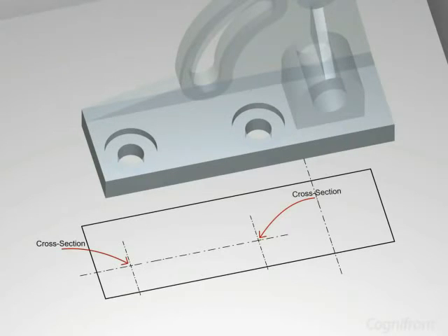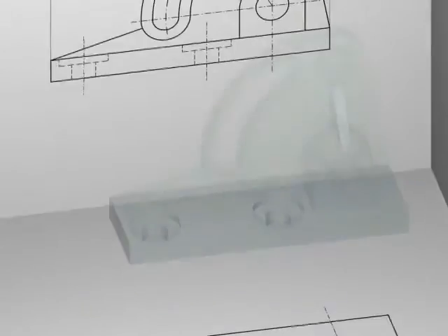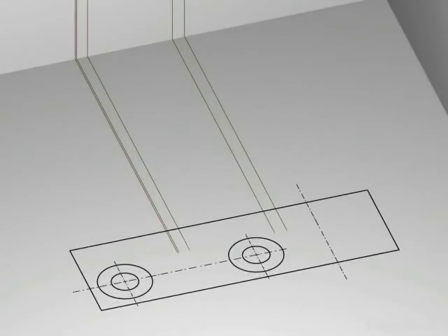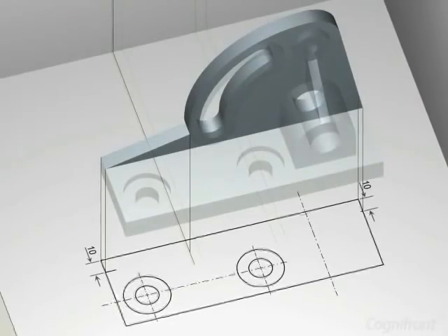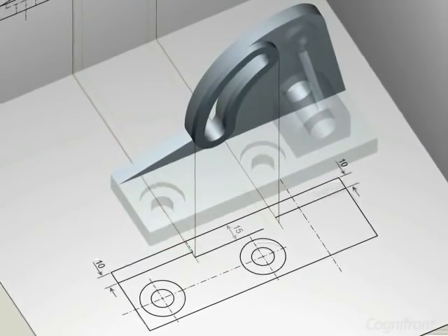Note the intersection points of this line with vertical center lines. Using these intersection points, draw two spot face holes with 30 mm diameter of outside circle and 15 mm diameter of inside circle. Now for inclined rib and slot, take reference from the front view. The inclined rib is 10 mm thick and slot portion is 15 mm thick.